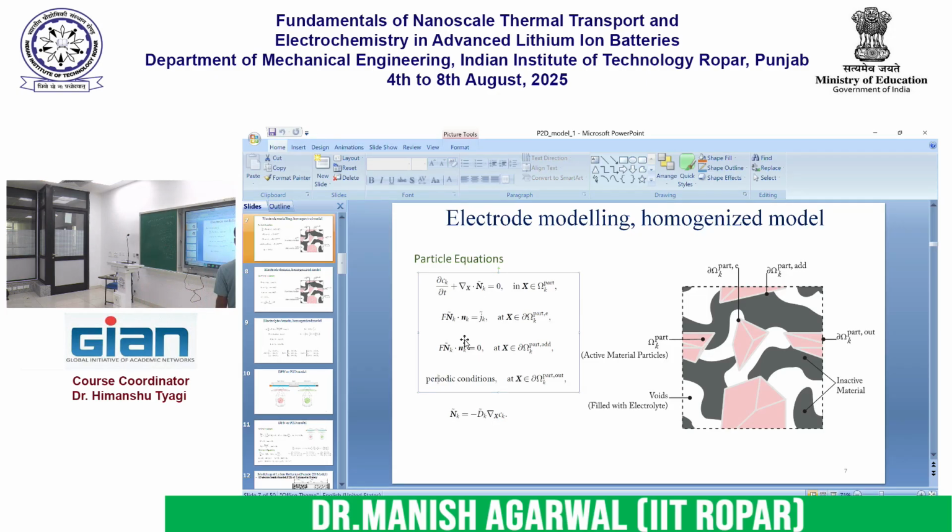In this boundary you actually take the periodic boundary condition, to denote that this is part of a much bigger domain. I will not go into too much detail, but the periodic boundary condition means whatever is happening at the top edge is happening at the bottom edge, and whatever is happening on the left edge is happening on the right edge.